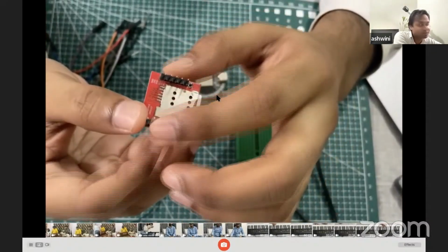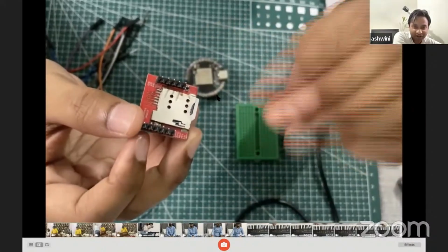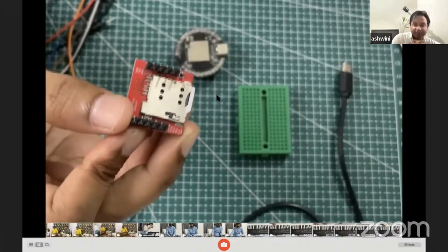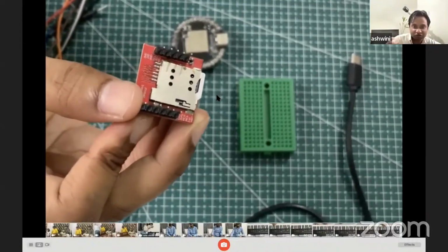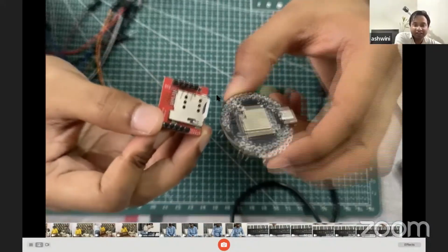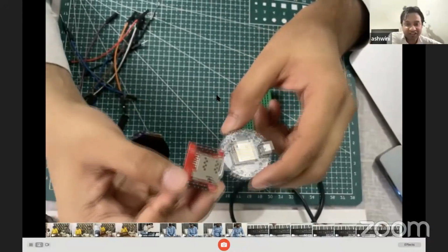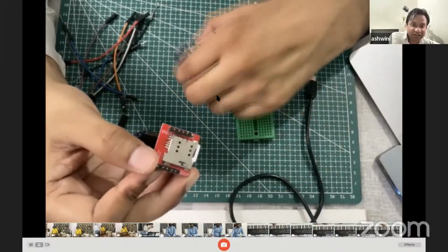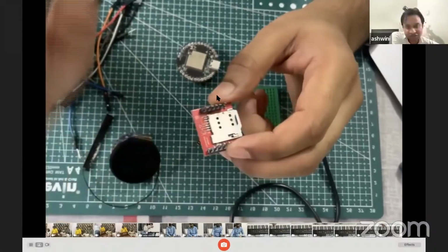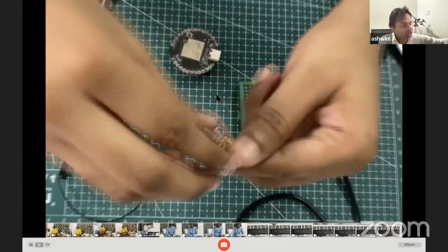If you connect the ring pin with a buzzer or any other kind of thing, then whenever you get an incoming call, it will start playing a tune or sound. Otherwise you can connect this pin to any GPIO pin of the Indus board coin, do a digital read, and check for the incoming call that way as well. So that can also be done. It depends on you.